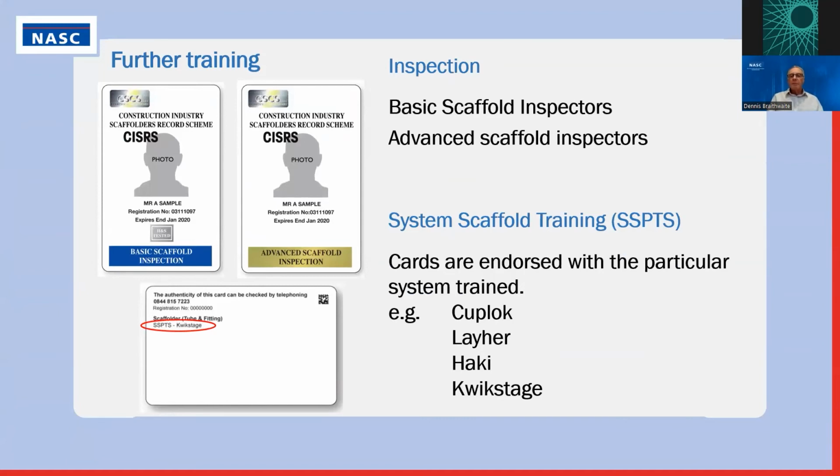Further training, as I said before: scaffolders, basic and advanced scaffolders, are considered competent to inspect the types of scaffolds that they've been trained for. Now, there's a slight proviso to that, in that the employer must also assess the competence and say, yes, he is competent to do that, from obviously his experience, and make sure that the scaffolder knows what he's doing, in effect.